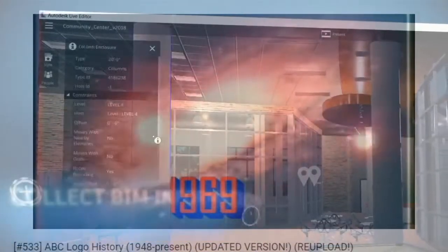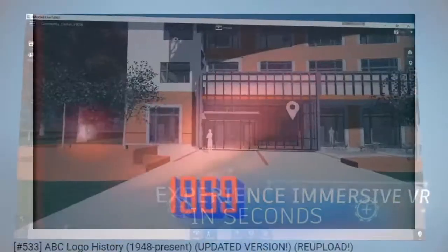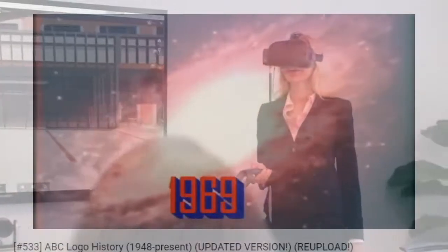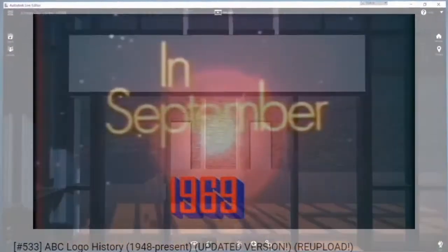The main floor object, in the figure that we're going to be showing you, has been cut with an opening at the inside face of the walls. Another floor has been modeled with a negative offset value to accommodate the thickness of the tile material, and the tile has been placed as a unique wall element. Now, it doesn't show you that, but you can discern that from an image.